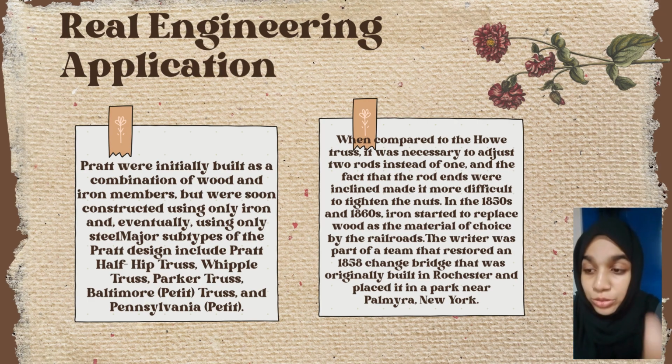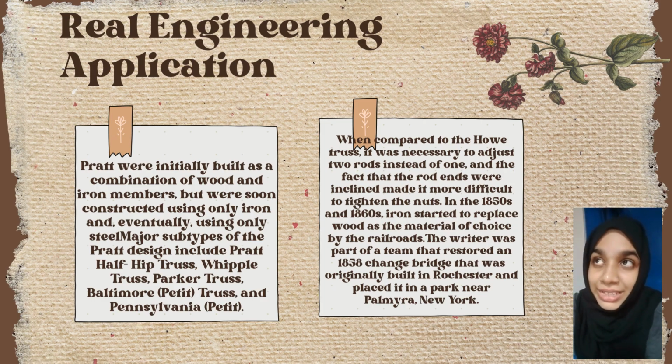Lastly, we have the two-span Fairground Avenue Bridge. This bridge has Keystone polygonal compression members connected by cast iron junction blocks and links for the main diagonal bars, counter ties, and links for the bottom chord.